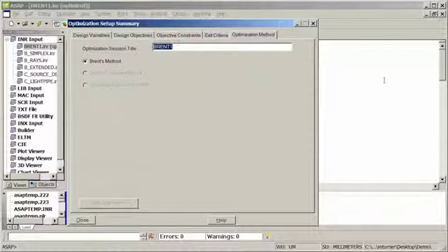Each user will be allowed to select the appropriate optimization technique for any given imaging or non-imaging design problem. These new tools are in addition to the optimization capabilities already within ASAP. In particular, we have added 3 new tools, one based on a Brent's method optimization technique. Brent's method is the tool that is appropriate if you have an optimization which only includes one single variable.